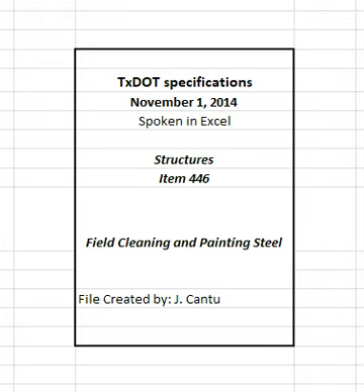Apply each coat of paint to clean, dry, firm surfaces complying with all specification requirements. Ensure surfaces to be painted are free of all forms of contamination. Ensure each coat fully cures to form a smooth, continuous, tightly adhering film of uniform thickness and appearance, free of sags, runs, pinholes, holidays, overspray, or other defects before applying the next coat.